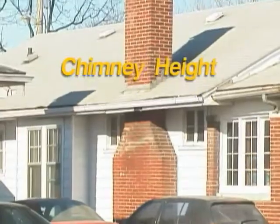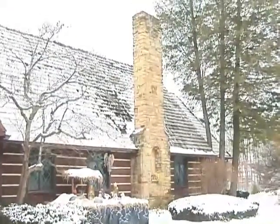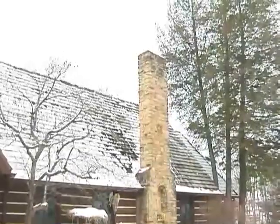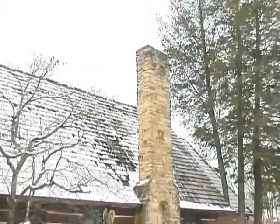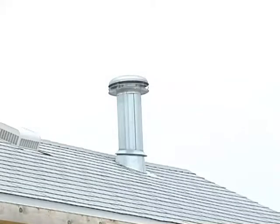Chimney height. The taller the chimney, generally the stronger the draft. To reduce wind turbulence problems, the termination must be above any nearby roof lines, typically 2 feet above any roof within 10 feet. This can vary, though, for B-vent, so always check the venting tables and your local codes.